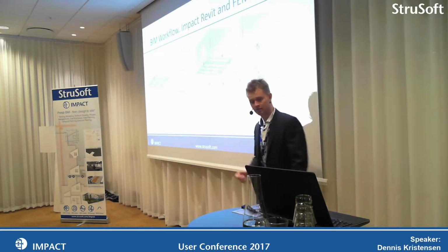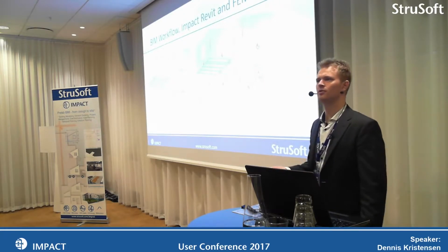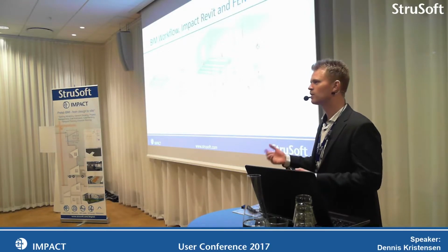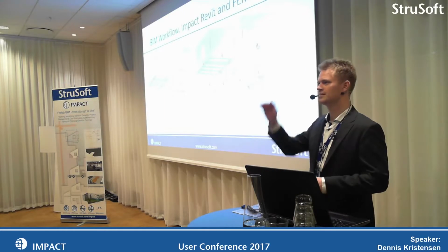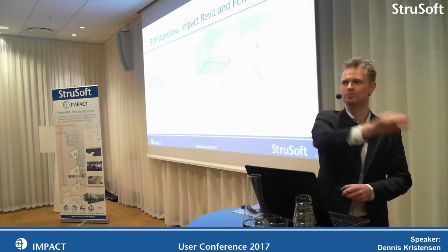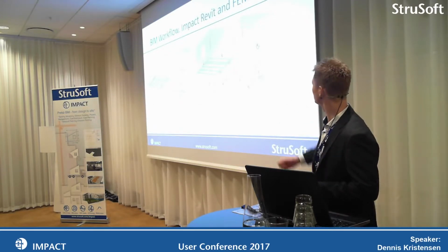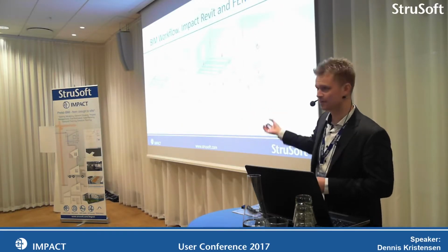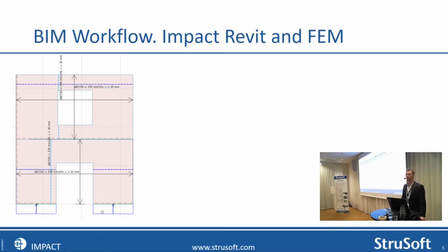We did this in a collaboration with a Danish company, and they said that they were tired of all this kilonewton per meter or stresses and colors. We want to know, if we put 100 kilonewton in wind load, I want to see that 10 goes into this wall, 10, 10, 20, 20. Easy. I need to get an overview of all these colors. So we made this. Now that we have the impact model in FEM design, and we have put on the loadings, the next natural step will be our reinforcement design.